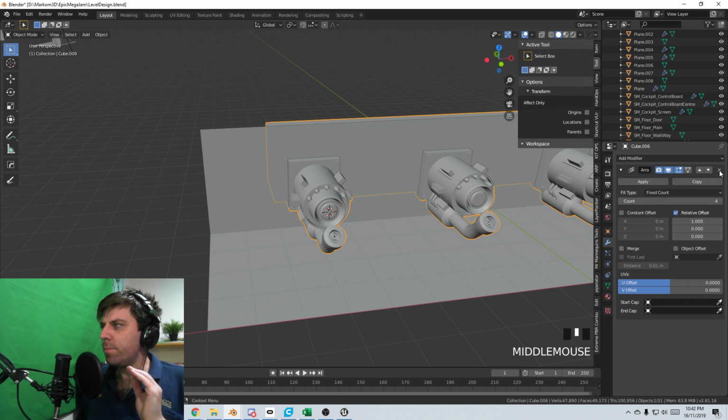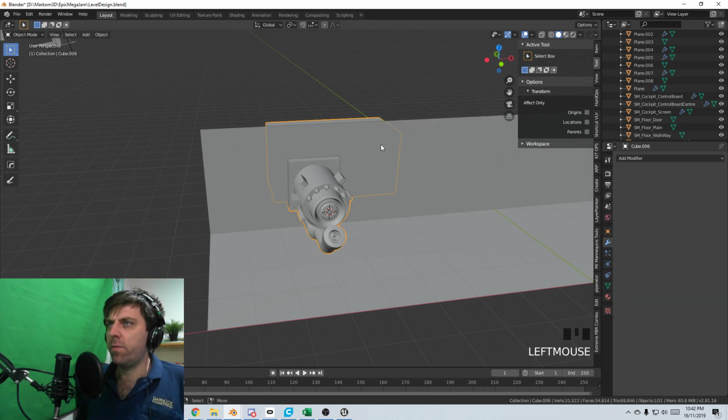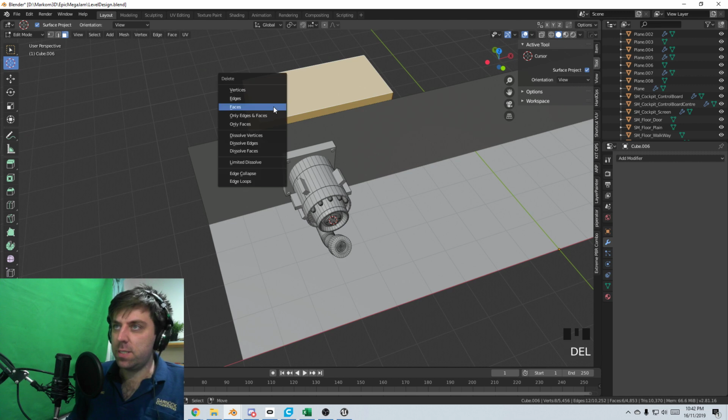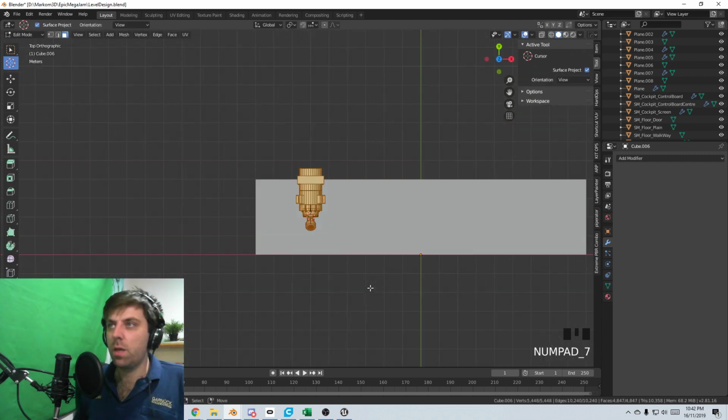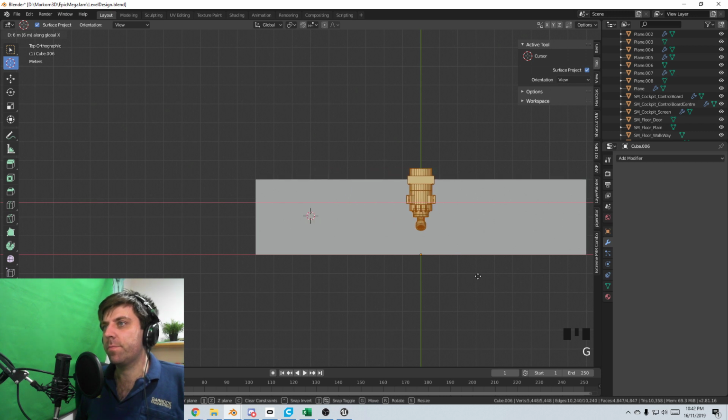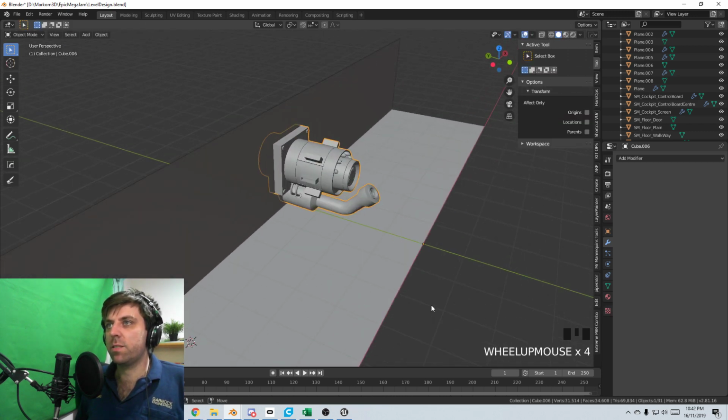Okay, let's delete the array. Let's now delete this box. Let's select everything, GX, and we'll put it like so.